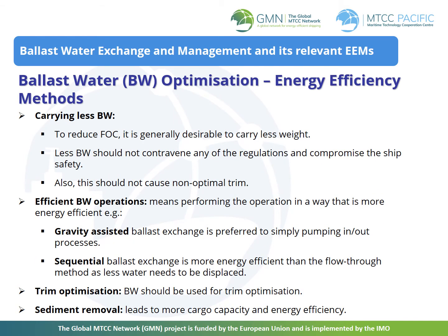Ships normally carry ballast water to ensure a ship's stability and safety. Normally, ballast levels should be adjusted to account for requirements to meet ship stability, steering aspects of the ship, and the optimum trim. This does not necessarily mean carrying lots of ballast water all the time, as this can unnecessarily increase the ship's displacement and thereby increase fuel consumption.